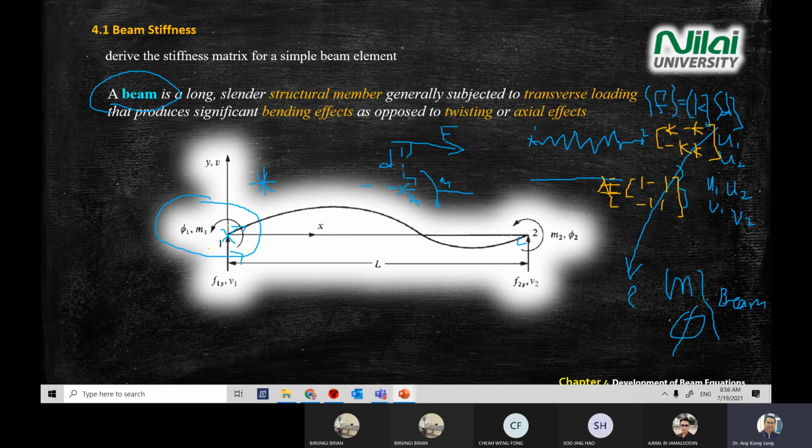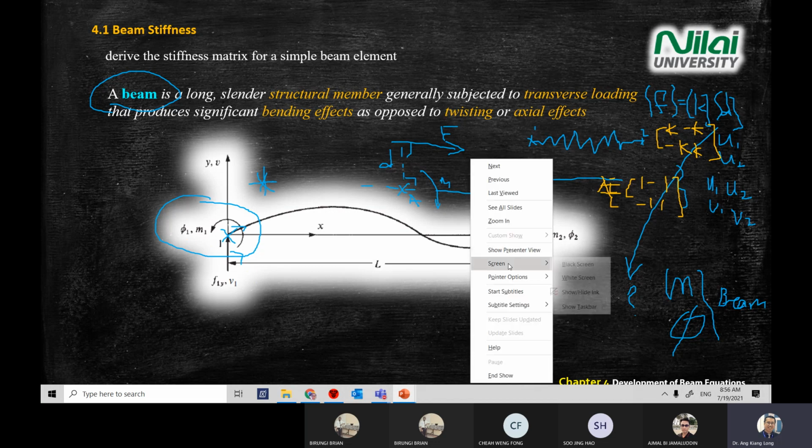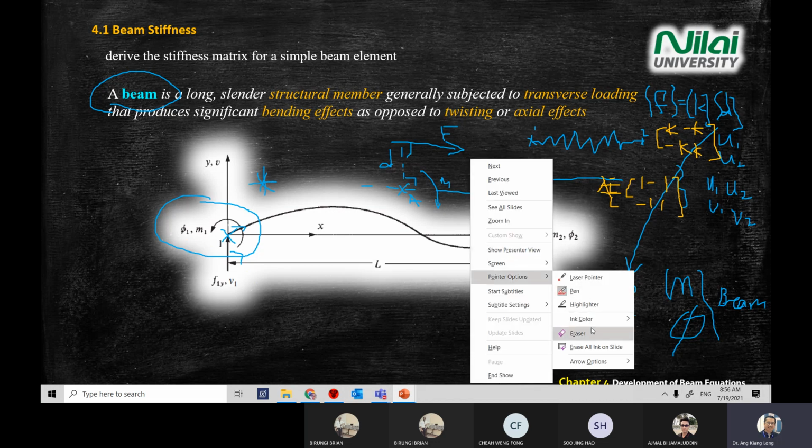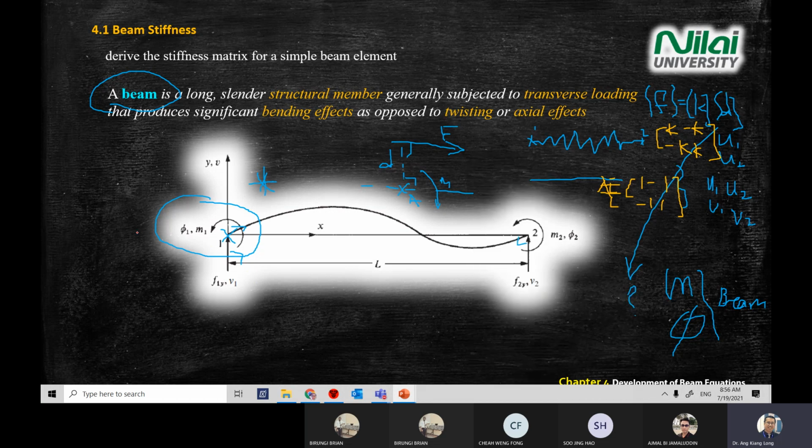So for beam, you have a moment and twisting angle. How do you get this twisting angle? Because of the characteristic of beam, the force in Y is generated at both points here. So you have M1 because of F2Y, and M2 here because of F1Y. You can have a lot of other forces on the body, for example F1x here, in the x direction, and F2x also appearing at the other end.